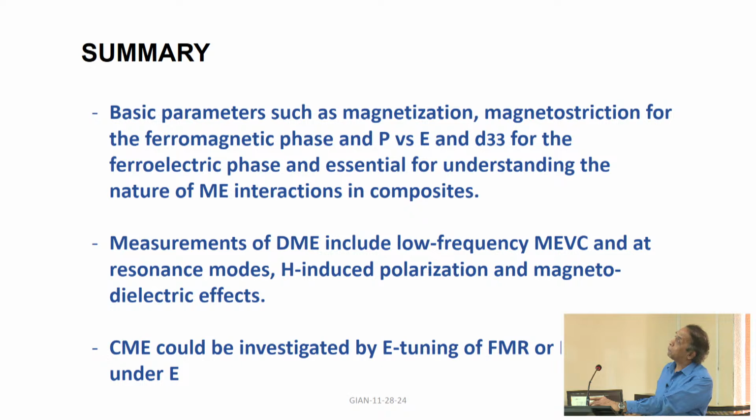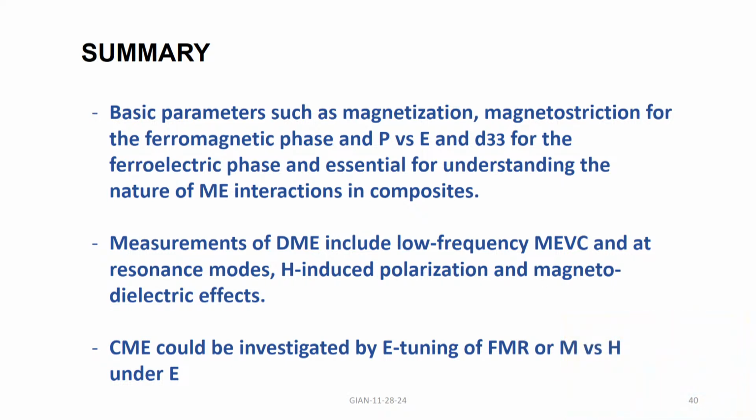Right. So, I will wrap up this section. I just talked about ferromagnetism and ferroelectricity, and we went through different phenomena associated with both kinds of materials. One, there is ordering of magnetic moments. The other, there is spontaneous ordering of electric polarization, and there is always a mechanical force associated with both, either in a magnetic field, which is magnetostriction, or an electric field, which is the piezoelectric effect.